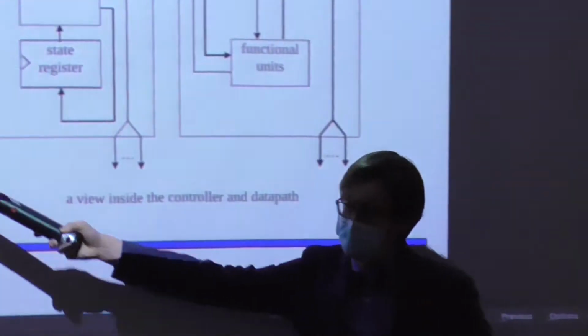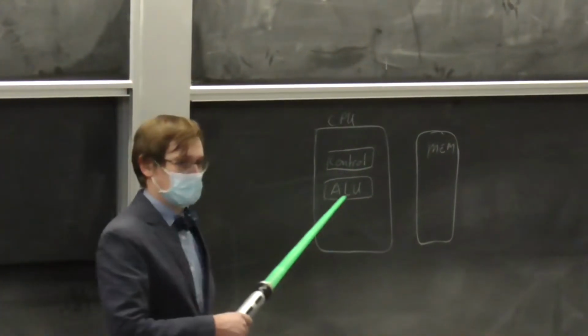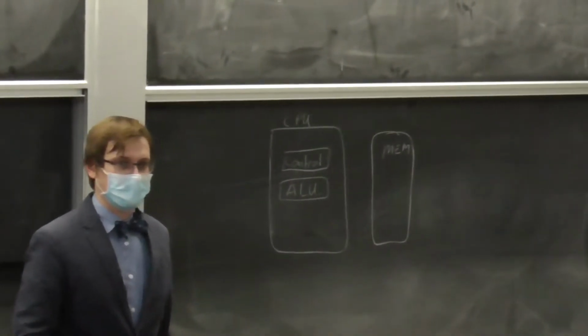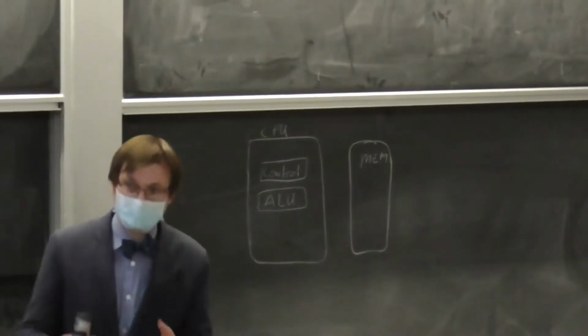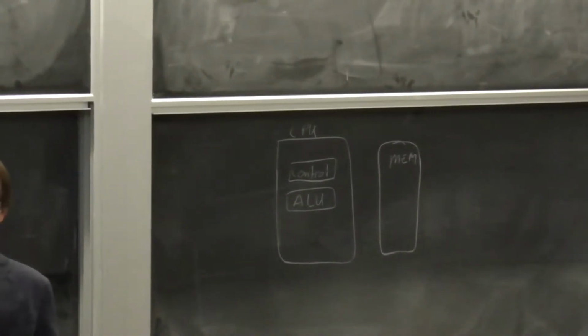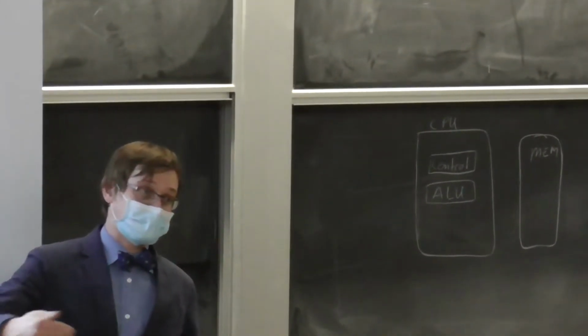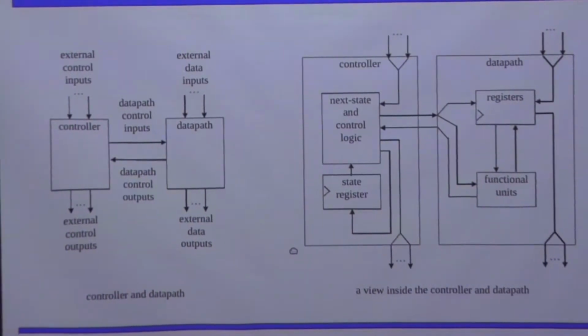The control unit does all of those little operations which select which memory gets loaded, which operations are performed, in what order. In addition, the control unit, at least in the case of general purpose processors, fetches and decodes instructions from instruction memory as well. It has to, because it's the thing that actually tells the ALU what to perform. So in order to tell the ALU what to perform, it has to know itself, and it gets that by looking up instruction memory. Make sense? Hopefully this makes sense. I mean, if this wasn't correct, then your phones wouldn't work. So, anyway.